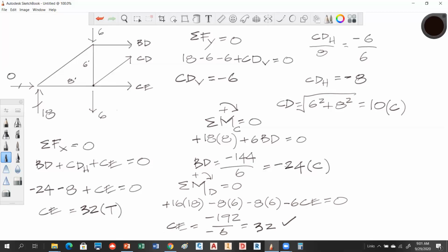So typically you can solve section problems with a sum of force in X, a sum of force in Y, and a sum of moment. That's all you absolutely need when you do these, okay? Sometimes you do require 2 moments. It just depends on what you're doing. Sometimes these problems will require 2 section cuts. It depends on which sections they're actually looking at.